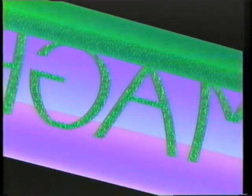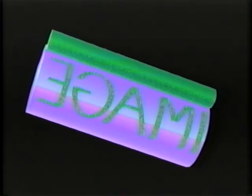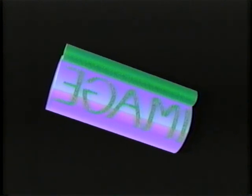As the roller turns, it brushes developer over the surface of the drum. Since toner has an opposite charge, it's attracted to the latent image. The toner particles are pulled away from the carrier beads onto the photoconductor. In this way, the entire latent image becomes coated with toner. Electrical attraction will hold the toner in place until it's transferred to a sheet of paper.